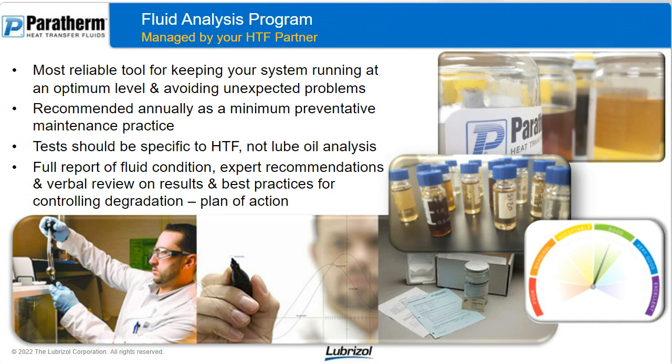Most of the time you can have that done either through or by your fluid supplier. So if you specified and used a reputable supplier, they're going to be able to set you up with good testing capabilities. Another really important thing, you want to make sure you have a full report of your condition. That includes expert recommendations, not just the values and if it's condemned or not.